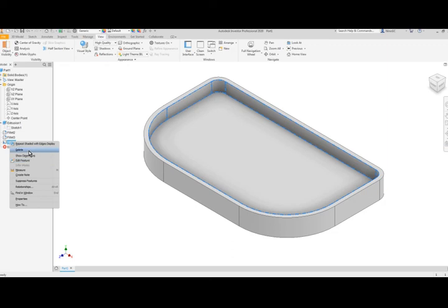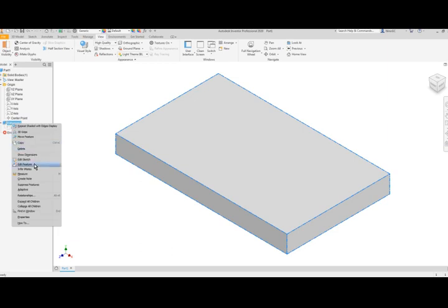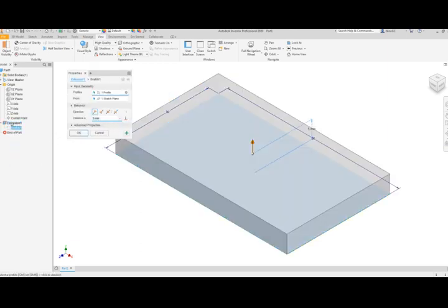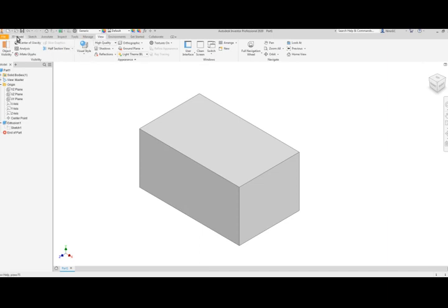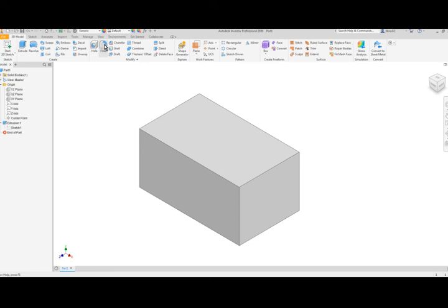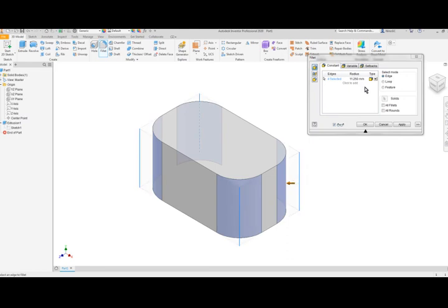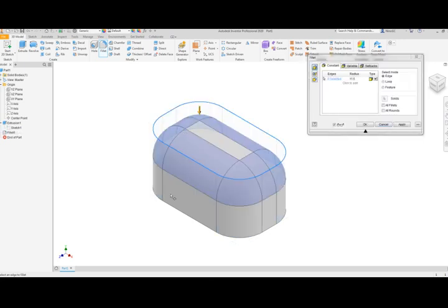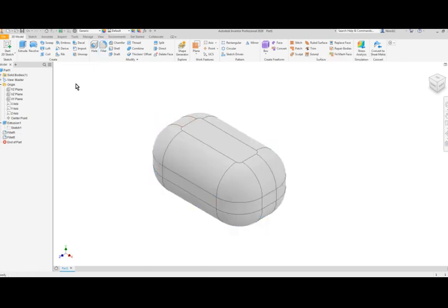With shell, we also have quite a bit of power. So in this particular instance, I'm just going to simply remove these two fillets. I'm going to increase the thickness of this particular rectangle. I'll make it, say, 25. So there's 25. I'm going to take my fillet, and I'm going to do the following. I'm going to select all four corners to start with, and I'll just give it a fairly generous fillet size of, say, 11.5. I go apply. Then I'm going to select that edge, and I'm going to select this edge, and I'm going to make those 10. Click OK. So now we have this particular object.